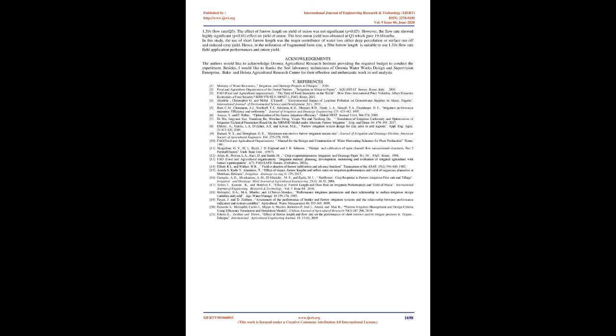The effect of furrow lengths and flow rates on distribution uniformity was highly significant, p<0.01. The highest value of distribution uniformity, 92.17%, was for the treatment combination of 25 m furrow length, F1, and 1.3 L/s flow rate, Q3, and the lowest value of 80.42% for 50 m furrow length, F3, and 0.7 L/s flow rate, Q1.